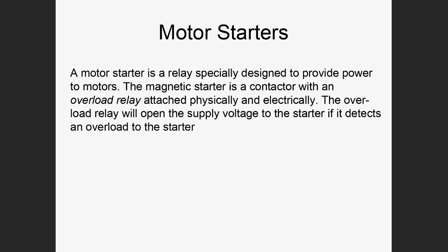After the contactor, there's something called a motor starter. So think of a contactor as a heavy-duty relay, and think of a motor starter as a contactor with an additional relay added to it for overload protection. And this is exactly as the name implies, used to switch heavy motors. It's a special type of contactor used to start or stop motors.